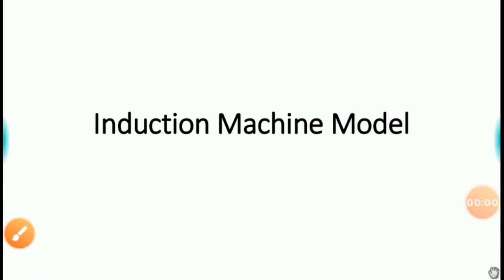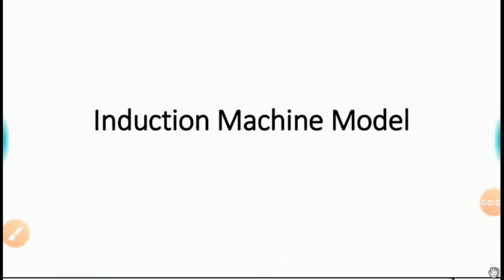Hello everyone. So just like the last video on synchronous machine, today we'll try to obtain a DQ0 model of induction machine, and we'll try to investigate the similarity as well as dissimilarity of induction motor with synchronous machine DQ0 reference model.